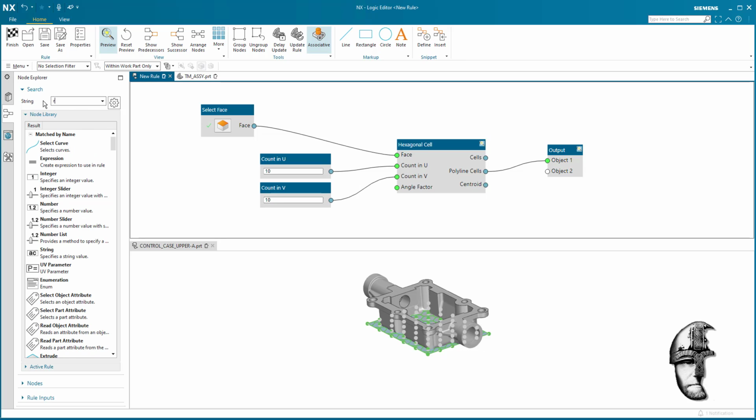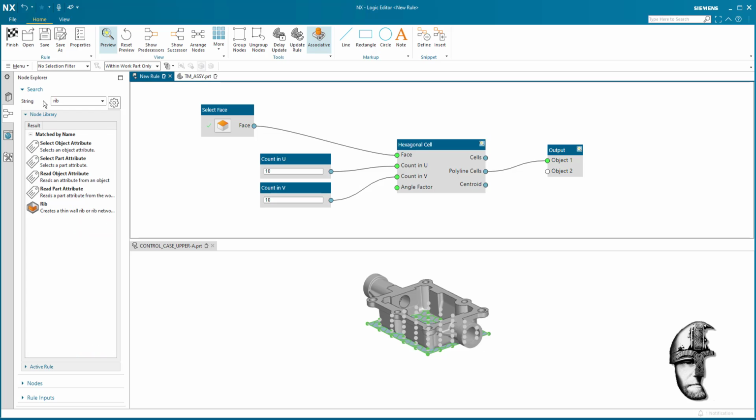I have a problem spelling here. Rib. We actually got the feature rib in there. However, that is best suited for when you actually have BREP geometry in there as well. Now this is faceted geometry, so hence I will do this as an extrude in a later operation. You will see why. So we say finish to that, and we're happy with that.